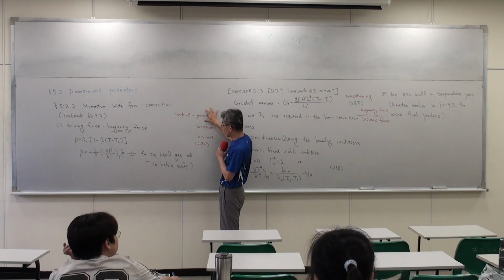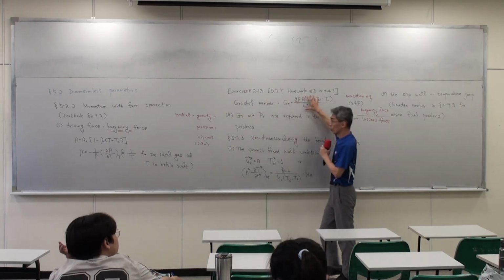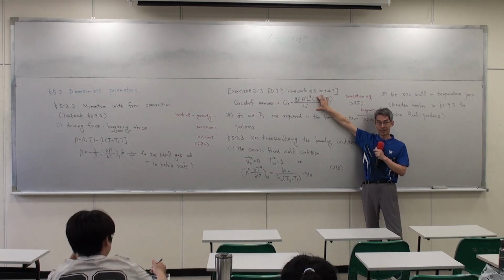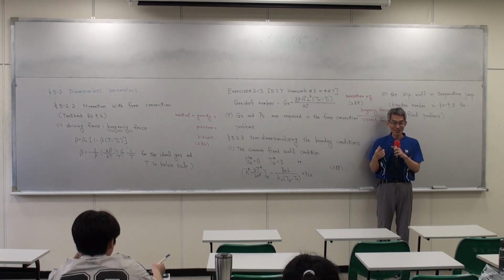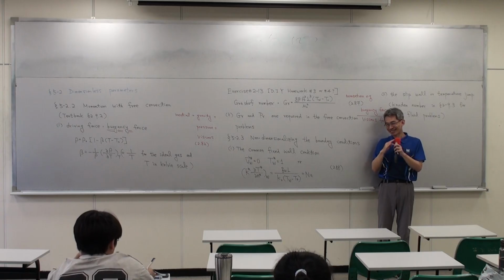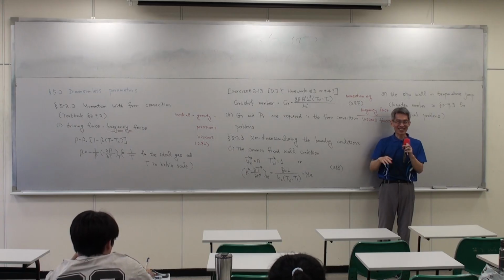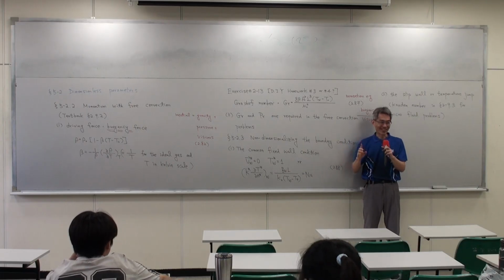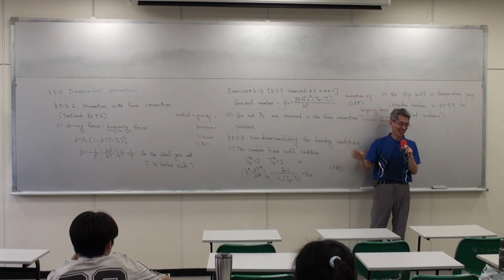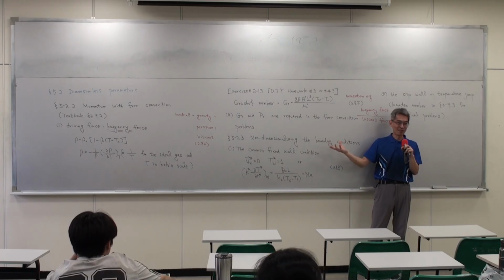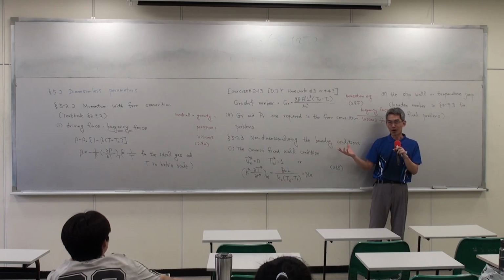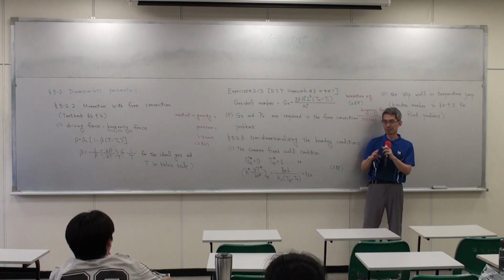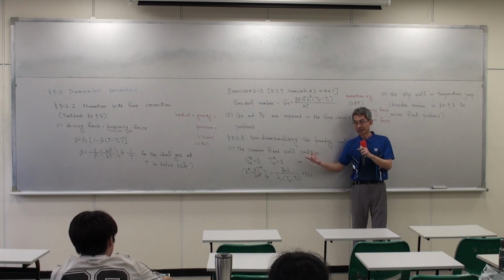In free convection, this term will become this term. Non-dimensionalization is not difficult, there are just lots of different arrangements. You can divide every term and come out with lots of dimensionless parameters, but some of them are repeats, and some of them are just inverses.